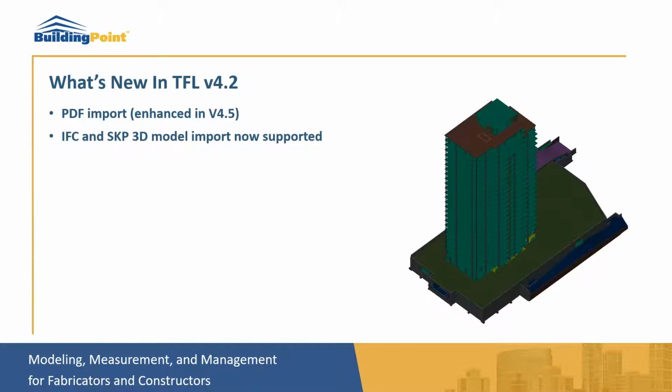They also added the IFC and SketchUp 3D models that were now supported for import inside TFL. So as you can see here on the screen, this is the 3D model of a condo tower that was made in Tekla. So we could now export 3D models, BIM models, directly from Tekla to an IFC format and pull this inside our tablet. Being IFC formats or SKP formats, they are lightweight and didn't lag at all in the tablet. We could orbit with these models, and it was just like a regular 2D drawing, no lagging.